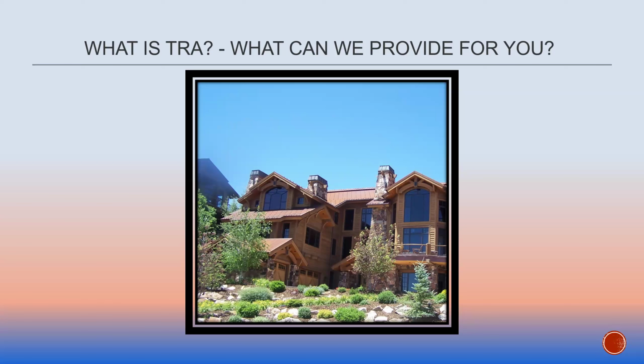I'm also doing a lot of work back east with contractors that are installing Tesla roofs. So anytime you're having glass panels on the roof, those types of things, snow retention needs to be considered. And as you get into the mountain regions, it doesn't matter if you're dealing with shakes, asphalt shingles, a synthetic slate, any type of roofing material. When you're dealing with large snow loads, if you have a sloped roof, you need to be considering what type of snow retention would be beneficial and weighing those risks versus rewards.